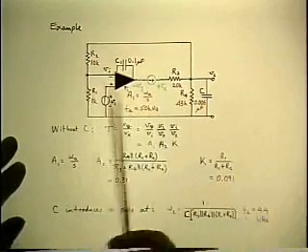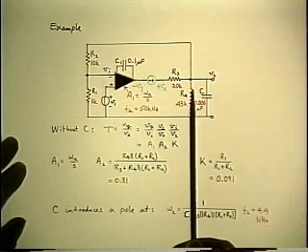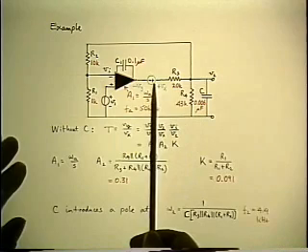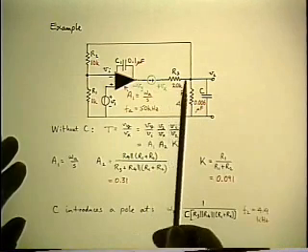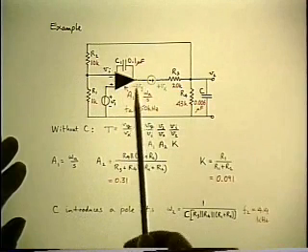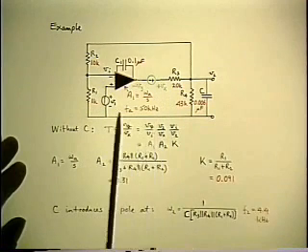Now I've got all the information I need to analyze for the loop gain, because I'm going to start with the Vx, which is at the right-hand side of the injected signal, and all I have to do is follow it around the loop to Vi and back to Vy using the gain of the op amp. And the loop gain is Vy over Vx.